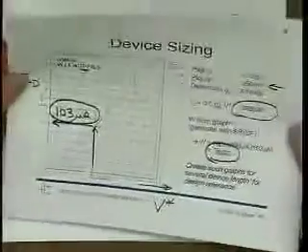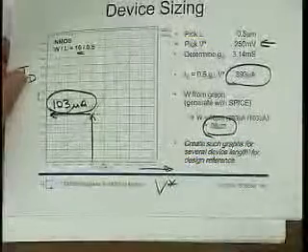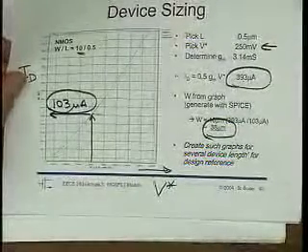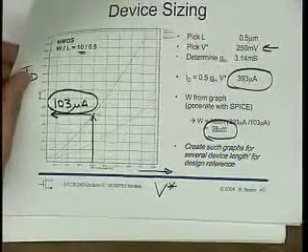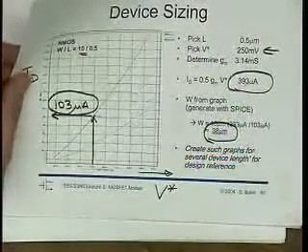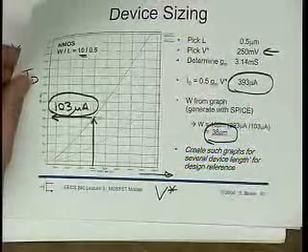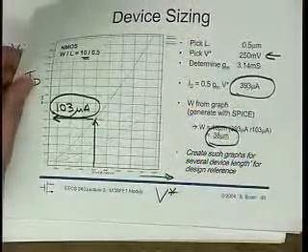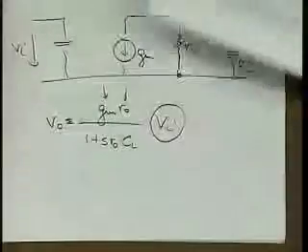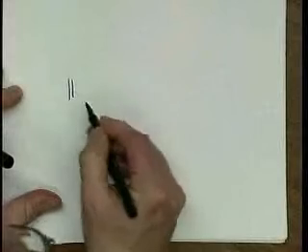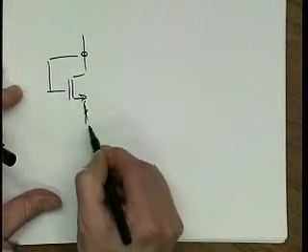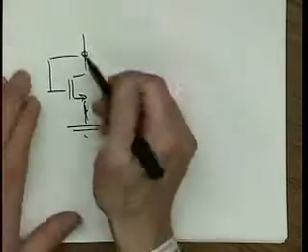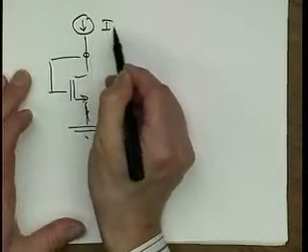How I make this graph? So first of all, I always make VDS equal to VGS, and the reason is that then gm doesn't really depend a whole lot on VDS, as long as we are really in saturation, right? And then in SPICE, I put my device in like that. Diode connected. It's really a strange circuit. And I drive it with the current ID.